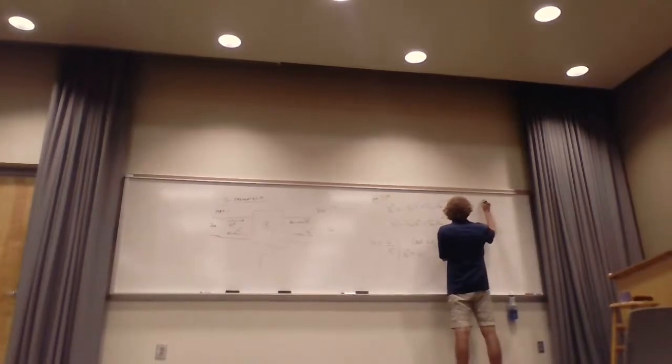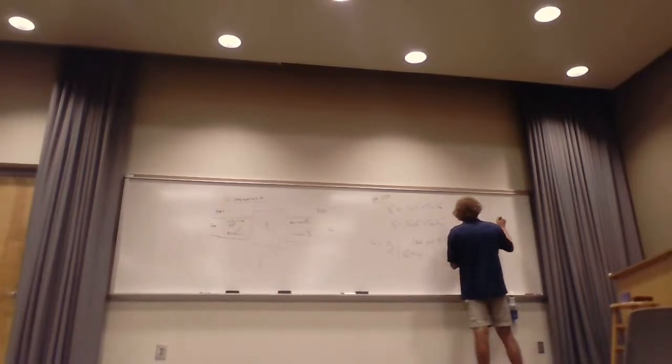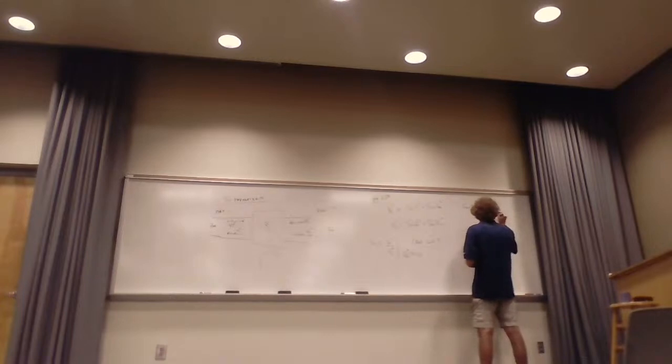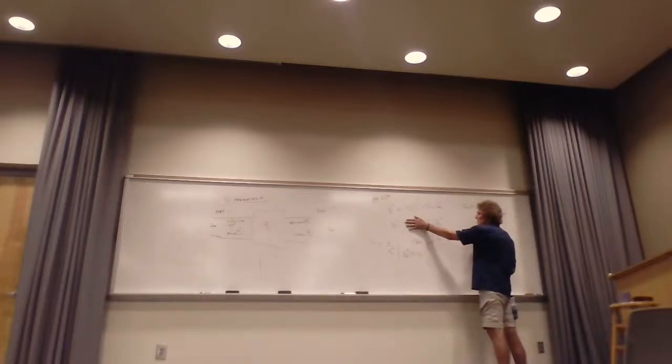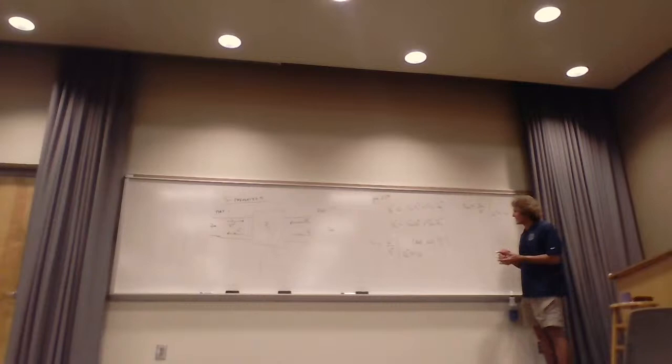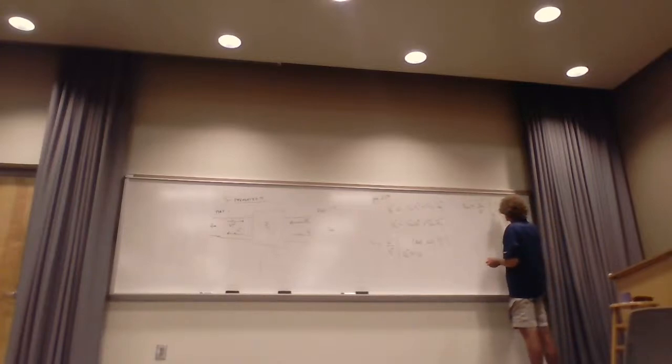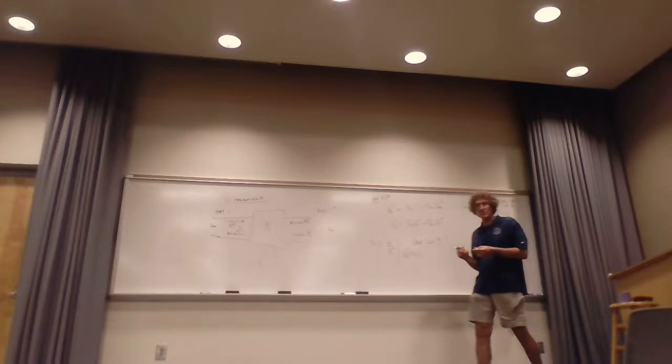S22 is equal to V2 minus over V2 plus, assuming that V1 plus is 0. Just look over here. V1 plus is 0. It's got to be, right? And that's really the reflection coefficient. I'll just call it gamma 2. It's the reflection coefficient at port 2.